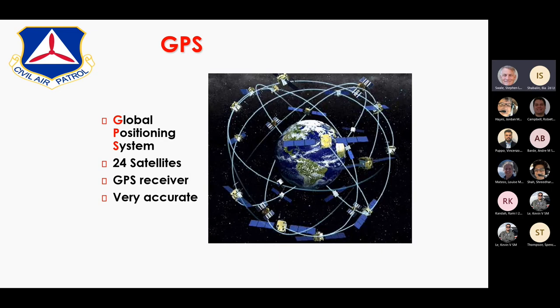You can put in one waypoint and automatically fly a point-based search using ground speed, cross-track error, and driving it using the heading mode of the autopilot. So much better to simply automatically put in a waypoint by pressing the enter button and then selecting that waypoint and then flying relative to that waypoint using the data strip information that I'm recommending, whether it be a G1000 on the MFD or if it's one of the aftermarket boxes that we've retrofitted some of our non-G1000 airplanes with.